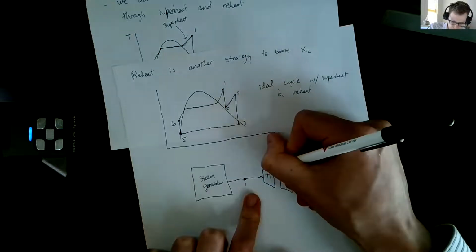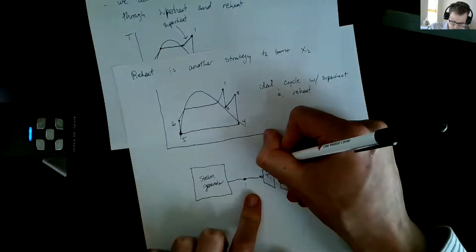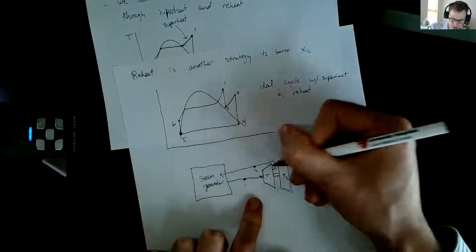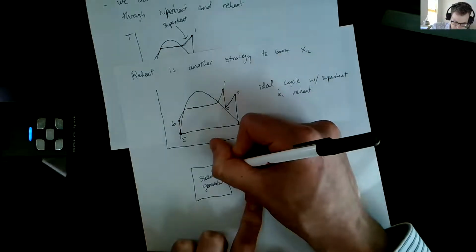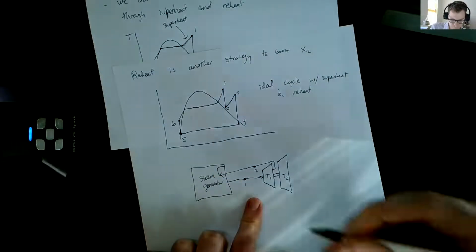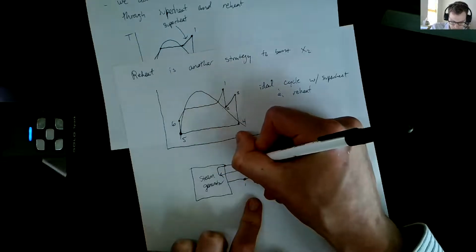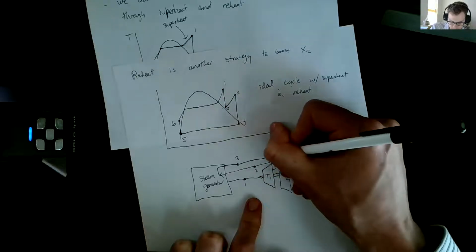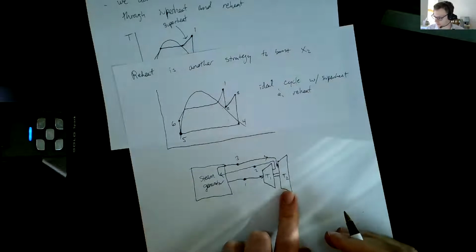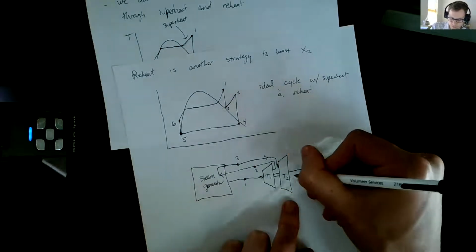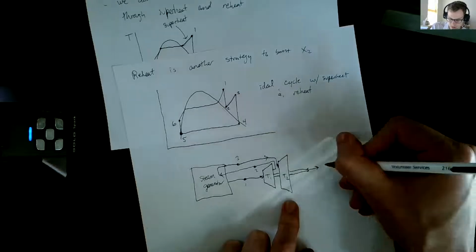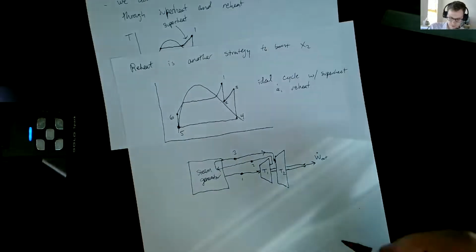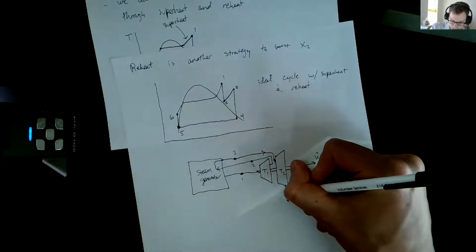Okay, the steam after it comes out of turbine 1 actually gets piped back into the steam generator. Okay, and so there's state 2 somewhere here. We run it back through the steam generator. After it comes out of the steam generator again, we're at state 3 now. We've heated it up. And then we come back in here and go into the inlet of turbine number 2. Here is where we extract our power, which is sort of like the combined power of the 2 turbines. And then out of the second turbine comes state 4.